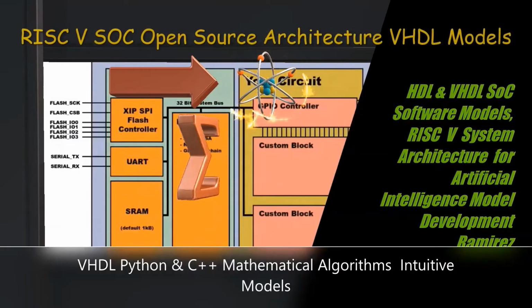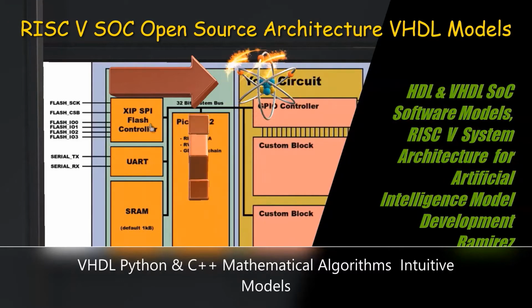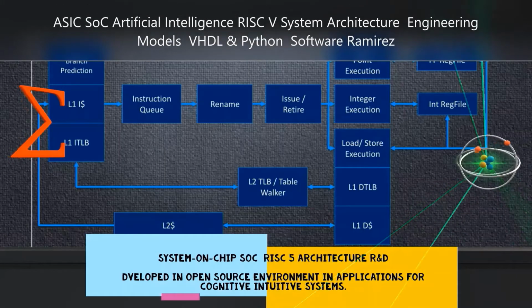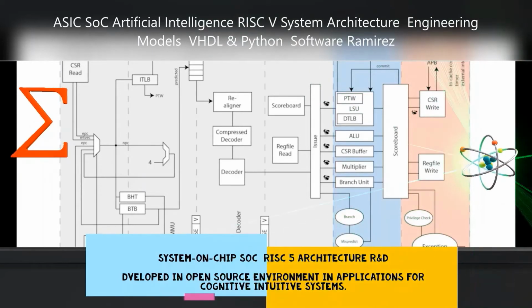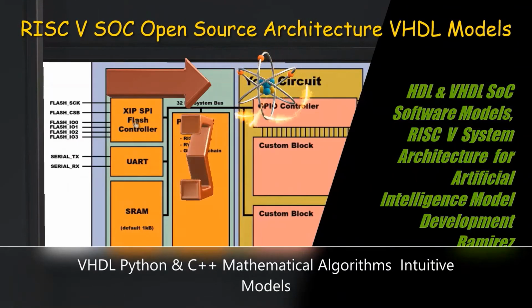System-on-chip RISC-V ASIC CPU pipelining architecture. Structural hazards usually revolve around the floating point unit, which may not be fully pipelined, while control hazards are usually more of a problem in integer programs, which tend to have higher conditional branch frequencies, as well as less predictable branches. Data hazards can be bottlenecks in both integer and floating point programs.